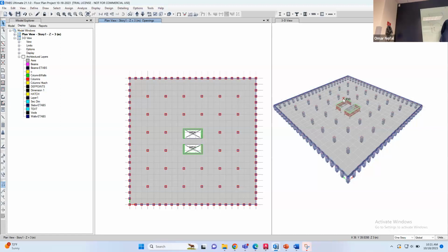This is how the shear wall is going to look if you were able to reach the maximum efficiency. Why? Because you made all of this shear wall have tension and all of this shear wall have compression. And how can we get this? By making this coupling beam very, very stiff, enough to make these two shear walls act as one shear wall.